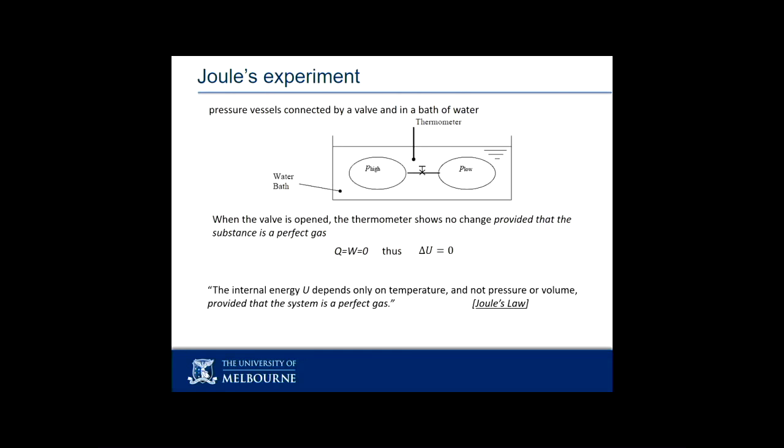And this is one we use in a perfect gas. The energy content, the sensible energy content, which we call internal energy, is defined by temperature. If I tell you the temperature of a perfect gas, I have told you its internal energy. That's powerful because temperature is easy to measure. I didn't need to measure the pressure or the volume of the perfect gas. That's very, very powerful maths. Experimentally, that's super powerful. Because particularly in a changing system, volume is hard to measure. Temperature is easy to measure.